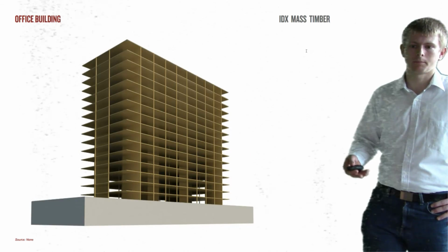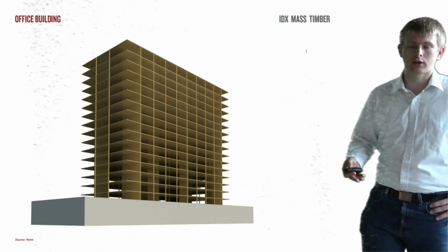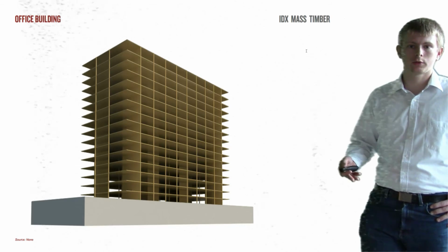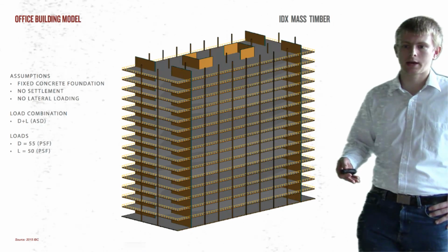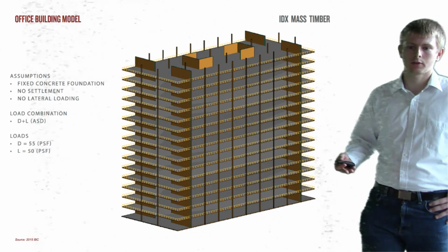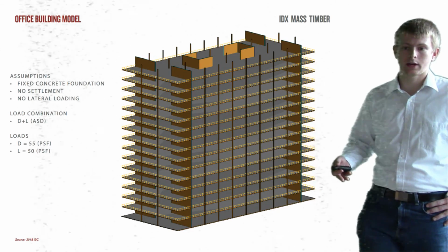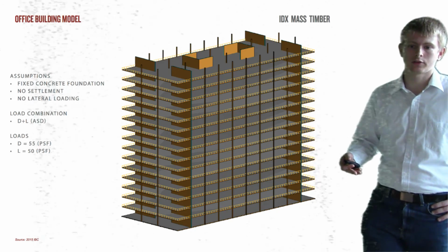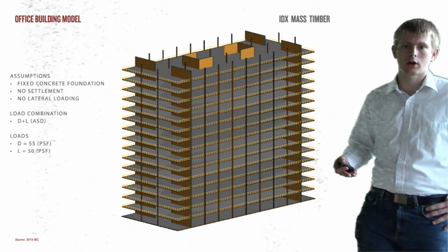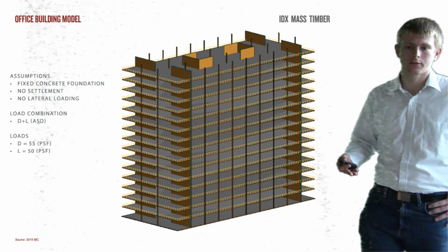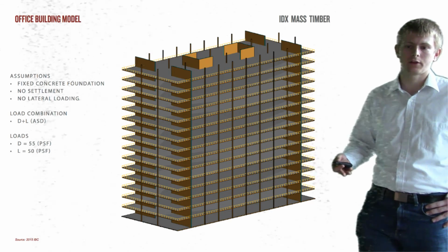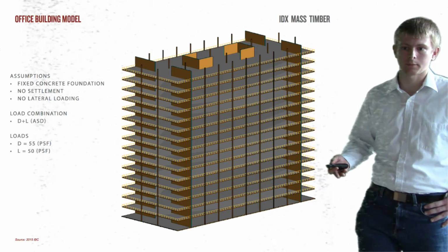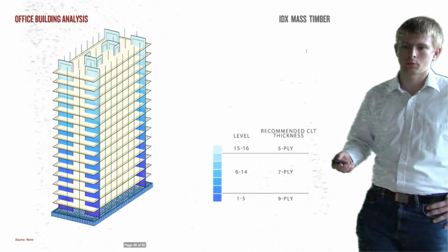This one was created by Jesse. It is the office building, and we did a similar thing. At each level we added dead and live load, with very similar assumptions, same foundation, no settlement, but notice that the loads have changed a little bit. For dead load, we estimated 55 PSF, and for the live load we estimated 50 PSF per ASCE recommendations. And we brought that in.